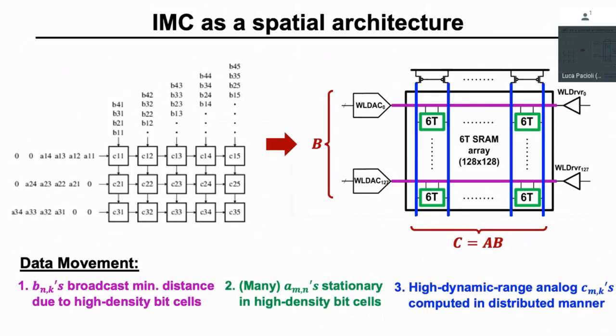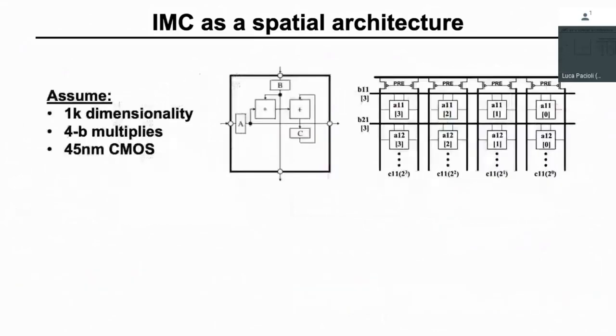On the other hand, in this case, of course, you do need to communicate this potentially high dimensional 16-bit, 24-bit, whatever the right dimensionality is, number to the edge of this array. So in terms of data flow, there's an opportunity here. In fact, it turns out in-memory computing also does some sort of an amortization of the compute. I'm going to describe this in a lot more detail. So this is that digital processing engine. I'm going to show you some real numbers that have come from both silicon measurement and also some careful post-layout simulations.